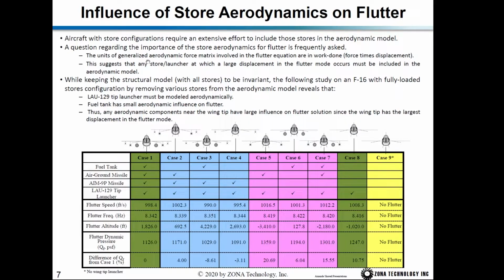This is because the generalized aerodynamic forces matrix involved in the Flutter equation is in units of work done, force times displacement. Therefore, any store and launcher at which a large displacement in the Flutter mode occurs must be included in the aerodynamic model.